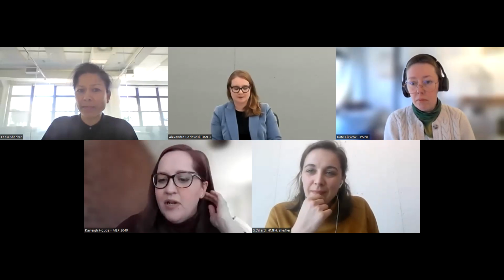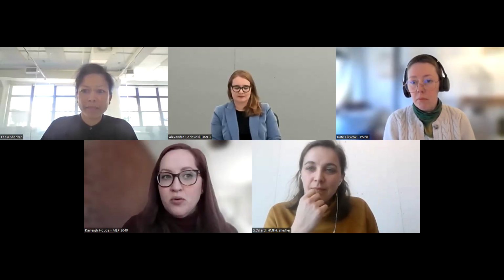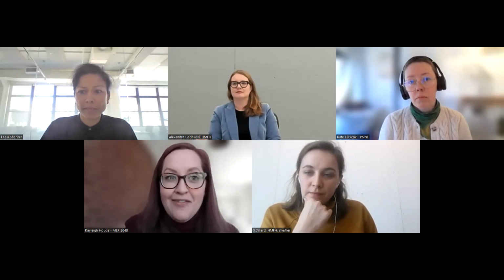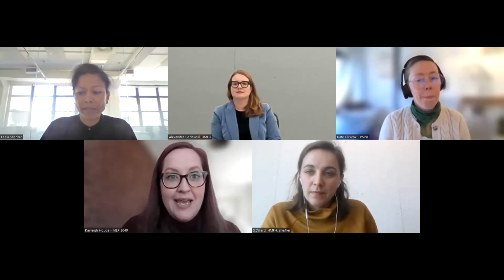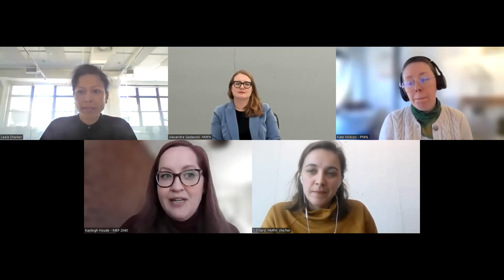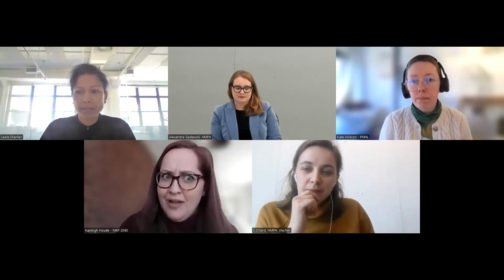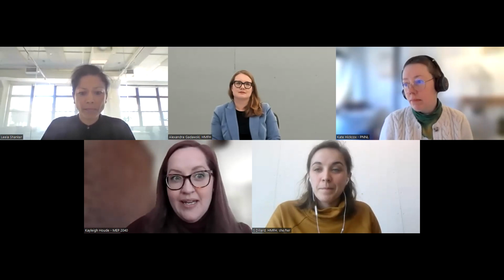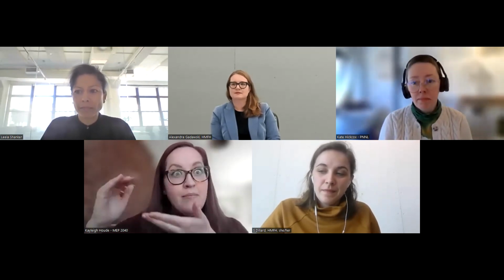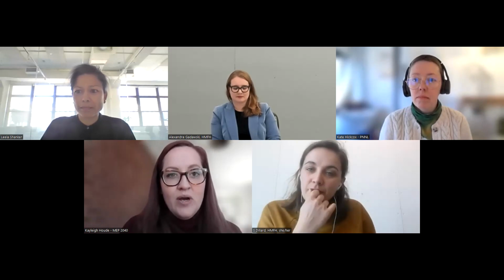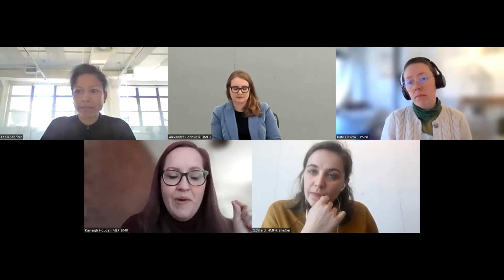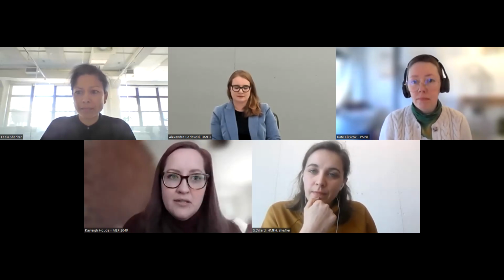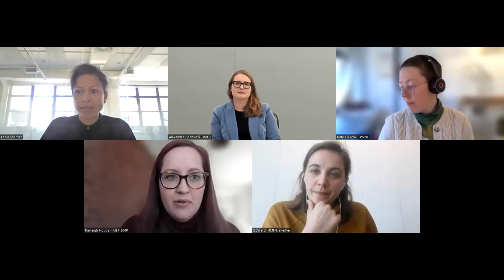Sure, I had a couple of notes just as people were talking. So through a tool like OneClick, you could perform a whole building LCA if you wanted to. However, the products that are given there, and as Kate pointed out, there are 500, let's say, MEP EPDs that are out there. They may not be, and likely will not be, for North American products. And North America deals on a very different grid than somewhere like Sweden, where the numbers on the embodied carbon side are much lower because their grid is much cleaner. So you're not going to get that kind of true picture of what a North American product's impact is. But if you wanted to understand relative proportions of products against each other, you'd be able to do a whole building LCA.